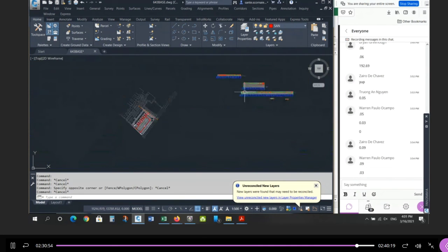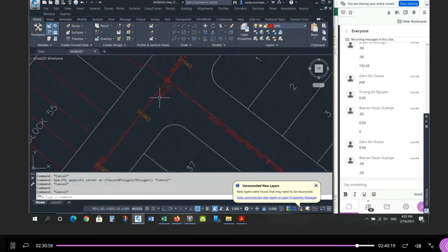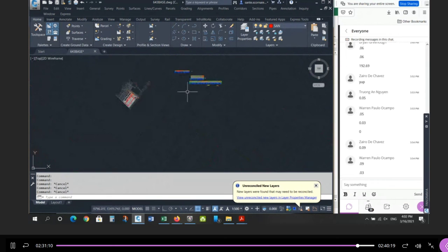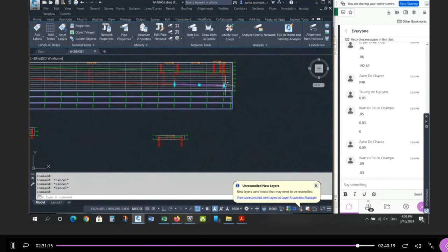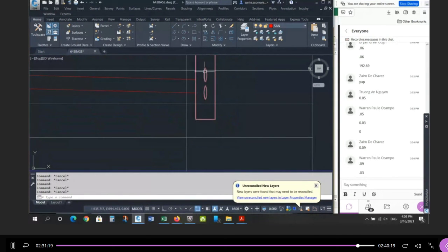If you go to the other street, let's go to the plan view. I drew this pipe, but I did not draw this one, and I did not draw this one. So when you look at the profile of street B, you should see this pipe's profile, but two ellipses representing these two connected at 90 degrees. And let's look at that, which is right at the end of street B. Here's the pipe profile on street B. You should see two ellipses in the maintenance hole. And there they are. They're cross-referenced.